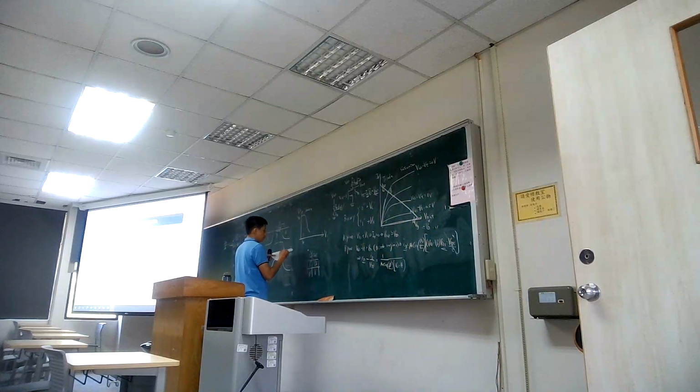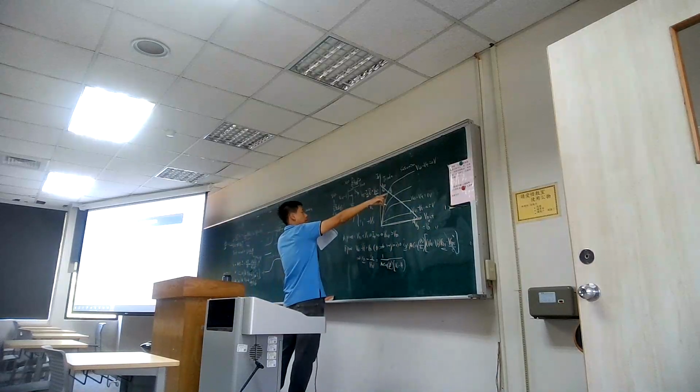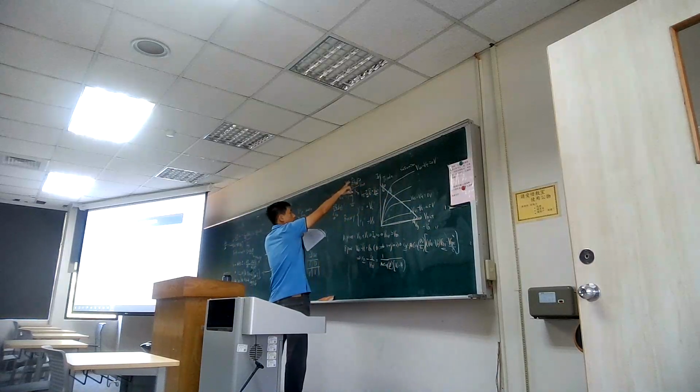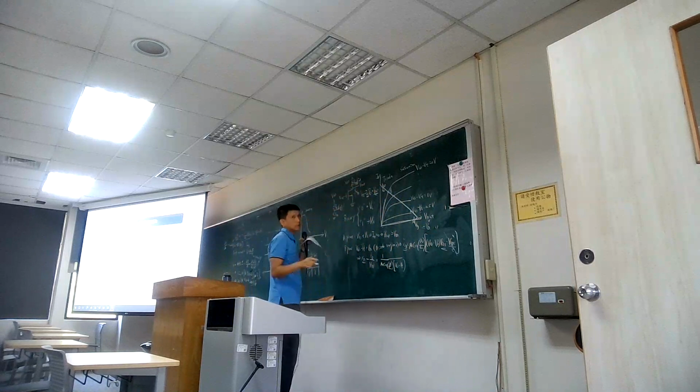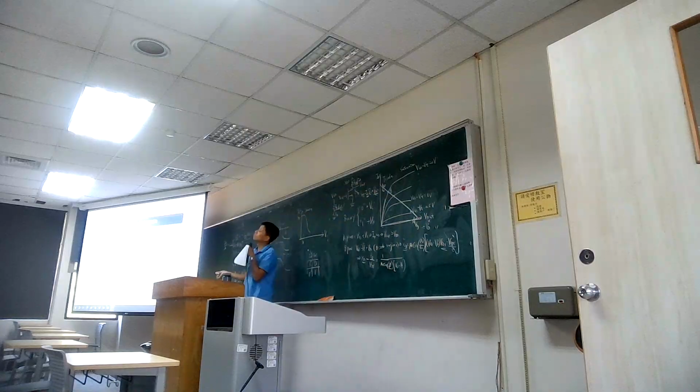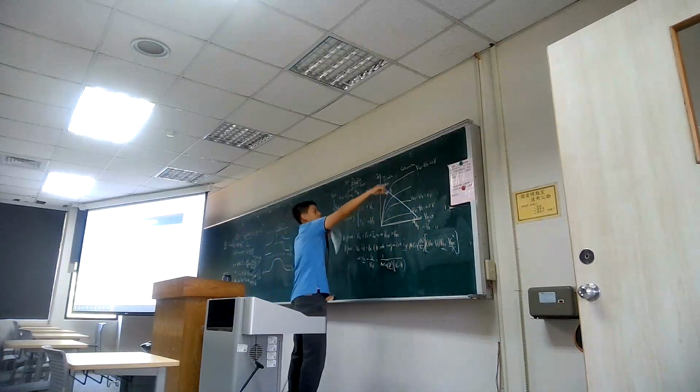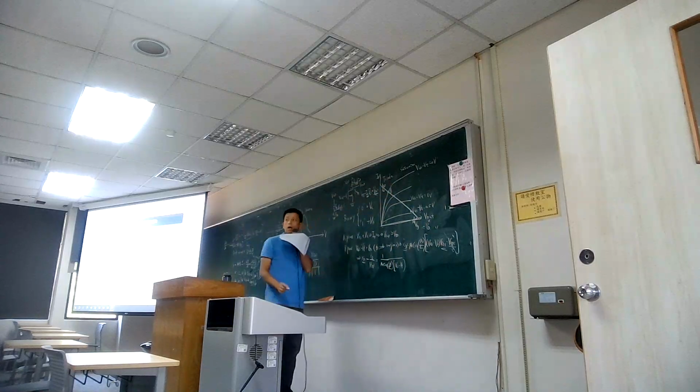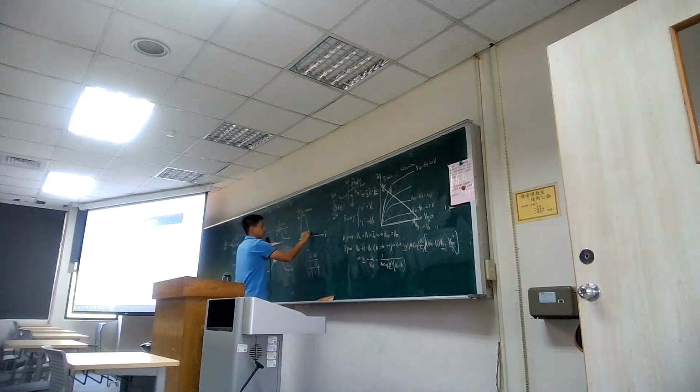And then it will go down till what position? Till the lower position, where the current is too high, so the voltage drop along RD is large. And this one is large, that means your VDS is no longer greater than VGS minus VT, depending on how much bias you apply for VGS. The higher VGS you apply, the higher VDS is allowed, right? Because you can see the triode region relationship. The higher the bias, the higher the voltage along VDS allowed. And for this one, later it will go back to VD.